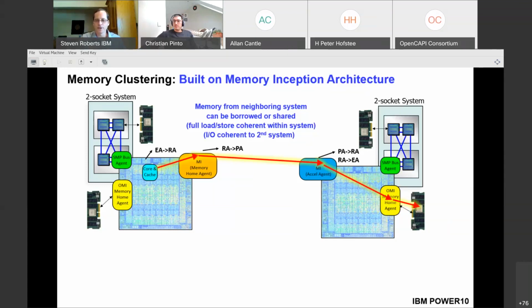I did present that reference as well at the bottom of the book, but it basically allows the borrower to target a physical memory address on the borrowed system, copy that into a hidden state buffer, and then paste that out to the memory agent with relaxed ordering rules to allow a physical copy into the memory agent and a transaction to be realized between the buses, a memory write, whereas the lender agent, the accelerator agent here, translates that into a DMA write into the OMI home agent.